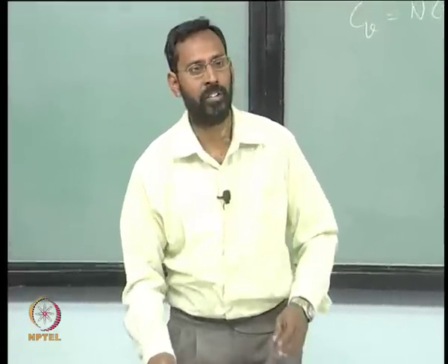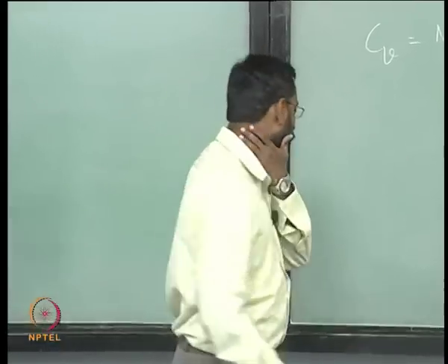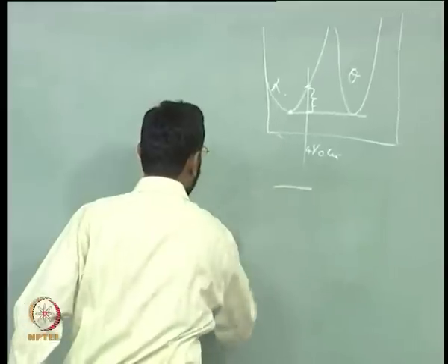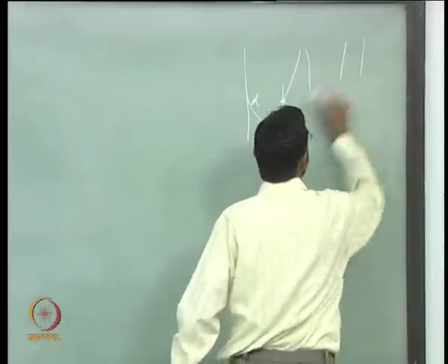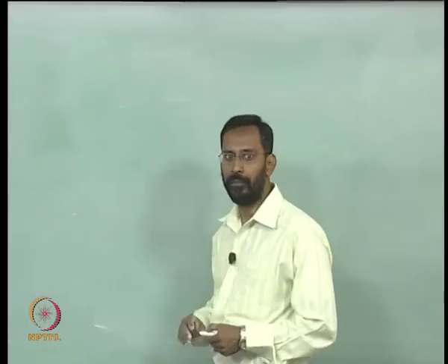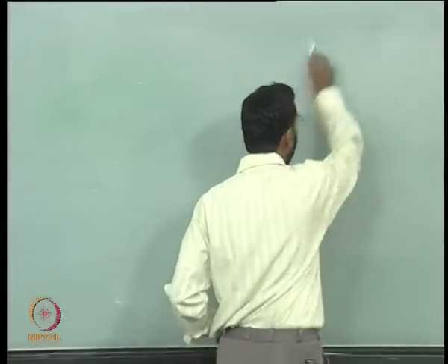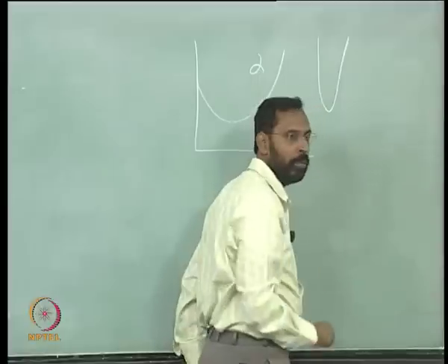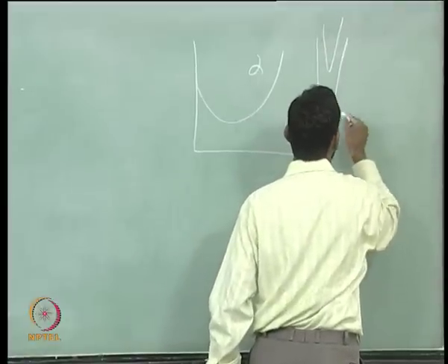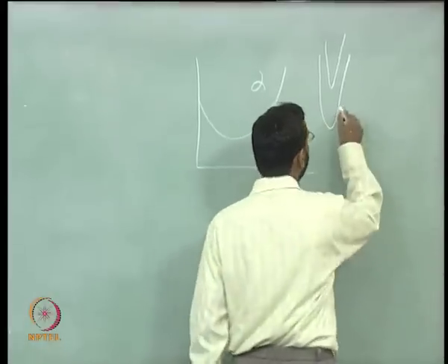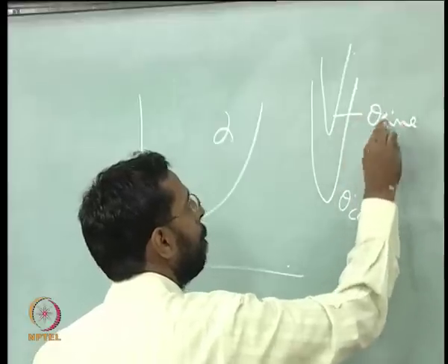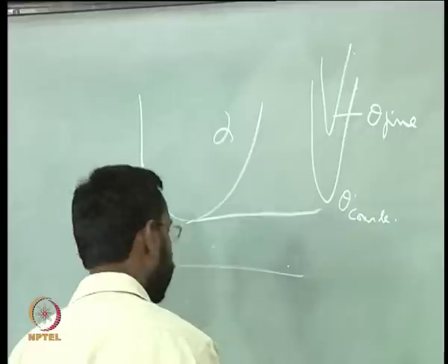Explain why uniform precipitates cannot grow. Half of you have done this, I think half of you could not do it. Basically you all should know that the driving force for particle coarsening comes only from the size difference. All of you know that if we draw the free energy composition diagram, if this is alpha, and if this is a coarse particle and this is a fine particle, let us call it the theta phase or whatever it is, then I draw a common tangent.